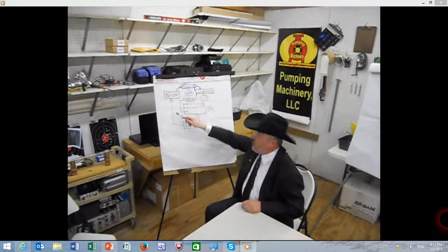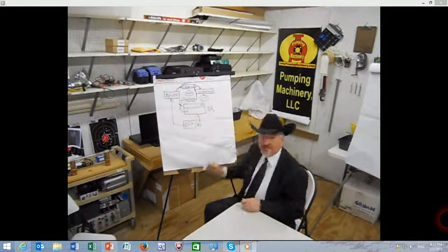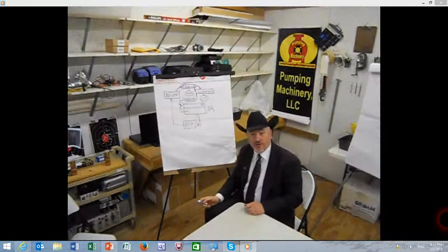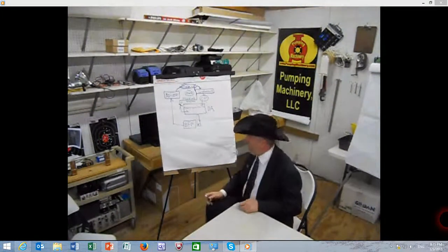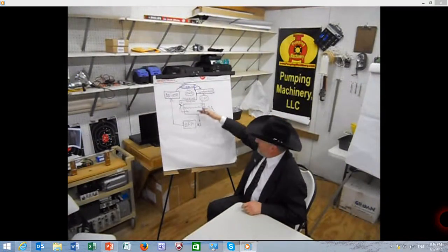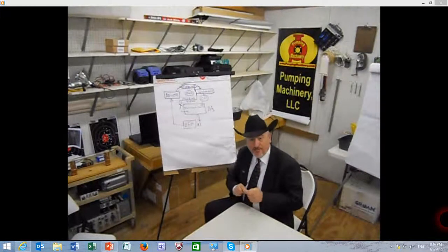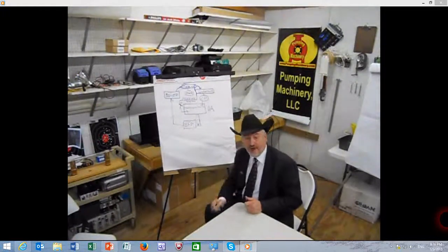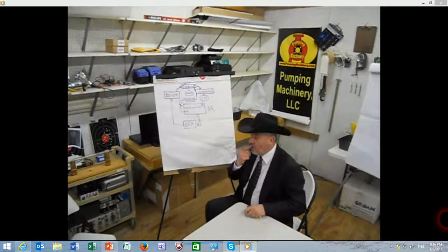And the load rejection causes sudden interruption of the steam. The condensate pump still continues, unfortunately in this example, to deliver cold water to the DA, and it flashes. Why it happens, we'll show in a minute from thermodynamics. The flashed water and reduced pressure cause insufficient suction pressure to the boiler feed pump, essentially lacking NPSH available, which becomes now less than required, and the boiler feed pump goes into distress. It vibrates, shuts down on PSH, so bad things happen to the pump.